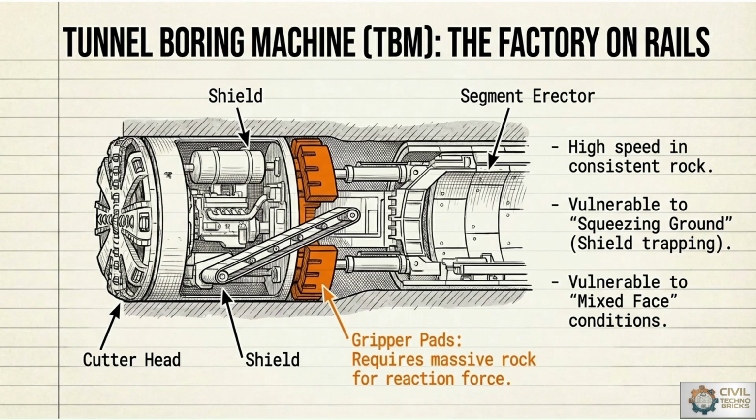So the subsurface investigations include drilling, borehole logging, trenching, and geophysical surveys. Core drilling provides information about rock quality, fracture conditions, and groundwater pressure. Geophysical methods such as seismic refraction, seismic activities, and electrical resistivity detect weak zones.